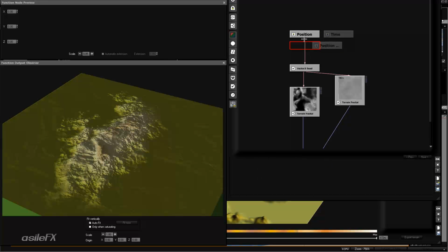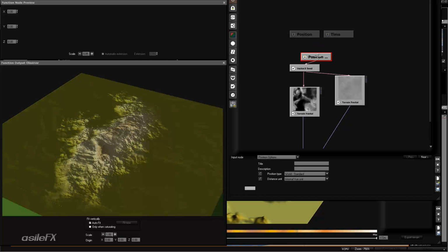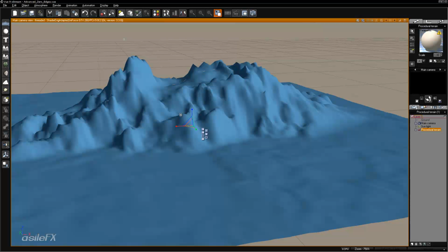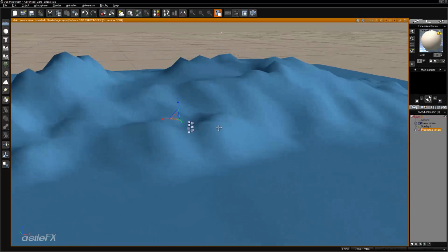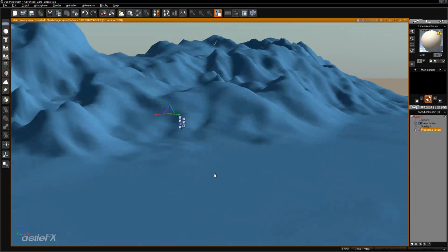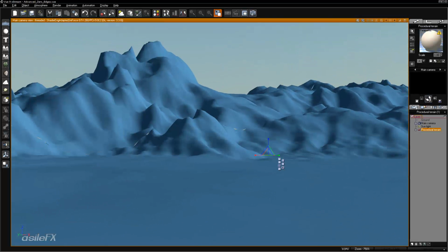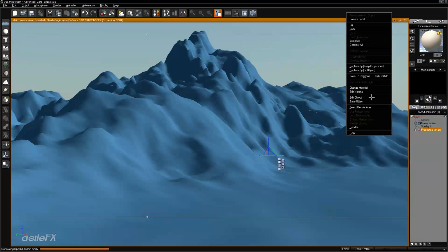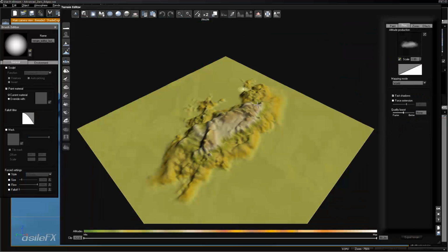Before I render, I am going to take that position input and switch it over to the position options world standards so that I don't end up with any strange artifacts or cracking, breaking, tearing, or holes within the terrain. It should help improve the quality. If it doesn't, and you've switched it over, you can edit the terrain and go into the quality boost.